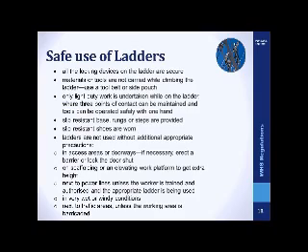You must ensure you have a slip-resistant base, and that slip-resistant rungs and steps are provided. You must also ensure that slip-resistant shoes are worn. Ladders are not used without additional appropriate precautions.